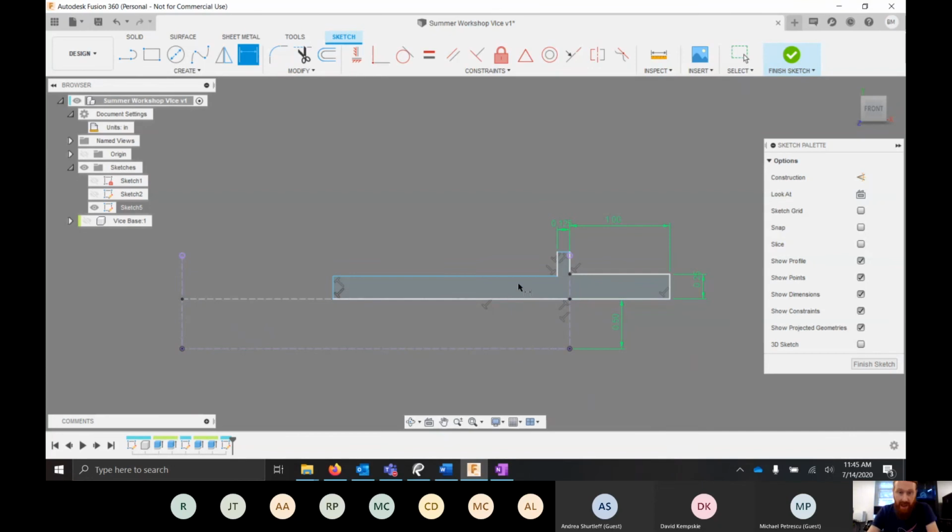And then this is a 1/2-10 Acme thread, so I'll just set that. I'll make that a 1/4 inch as well. And we need to set this length to 1 7/8. And then this little round part here is a 3/4 inch diameter, so I'll set that as 0.375 as half.